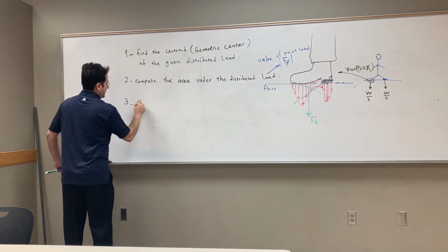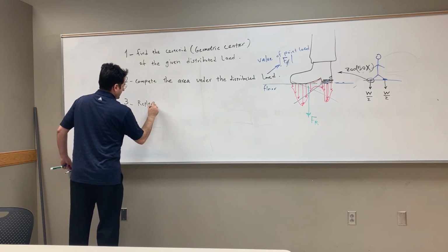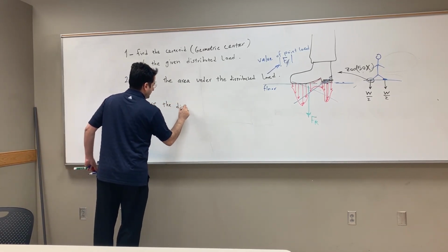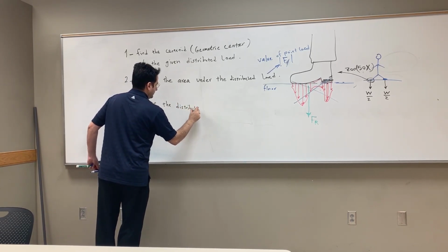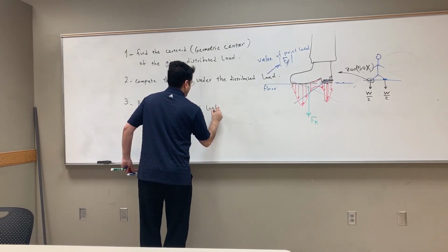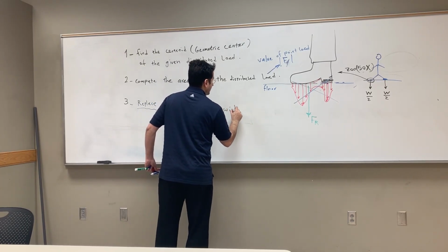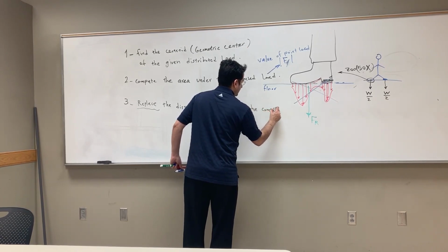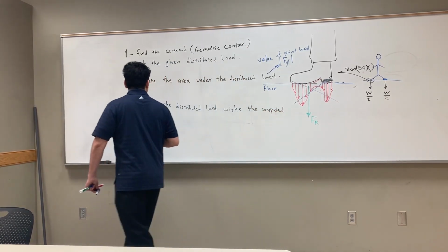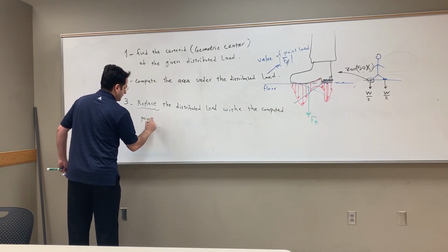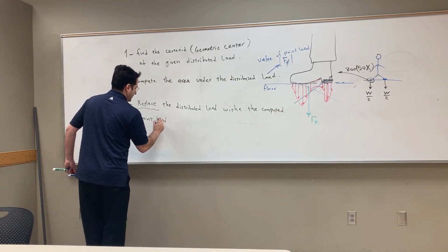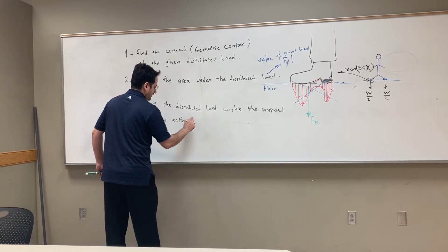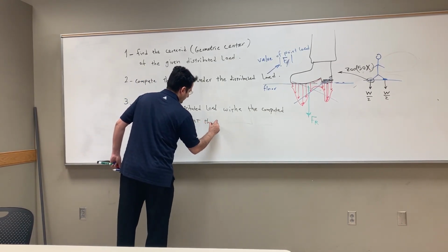Step three, replace, this is the important thing, replace the distributed load with the computed point load acting at the centroid.